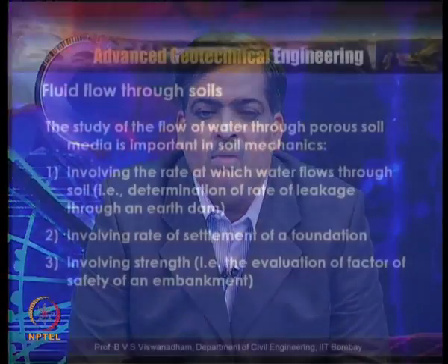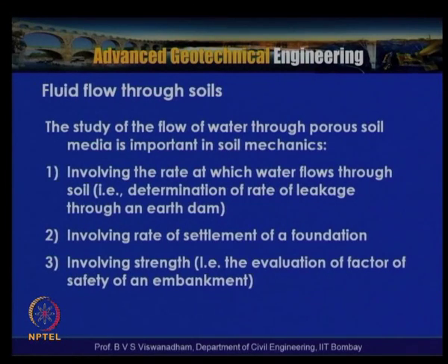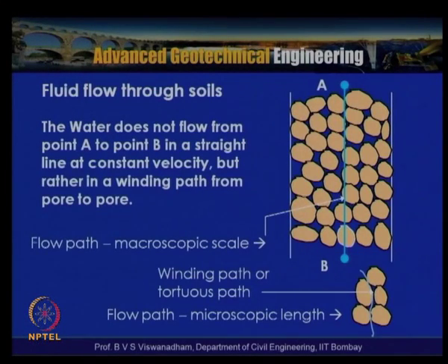So, from the fluid flow point of view in construction, we are interested in the rate at which water flows through the soil, that is, the determination of the rate of leakage through an earth dam, the rate of settlement of a foundation, or the strength gain, that is the evolution of the factor of safety of an embankment or a dam which is being constructed on a soil.